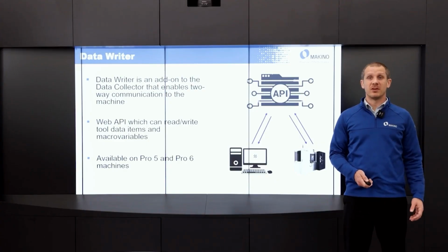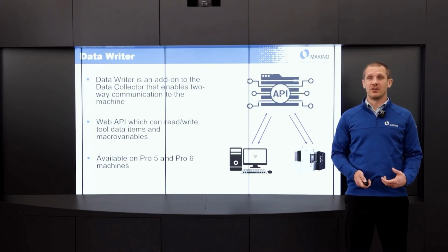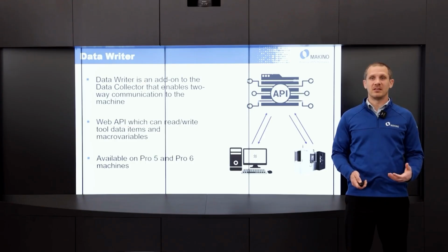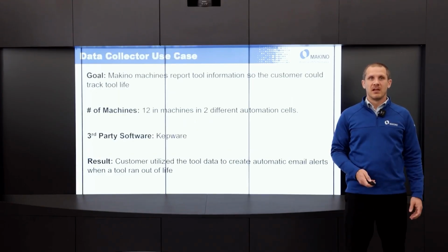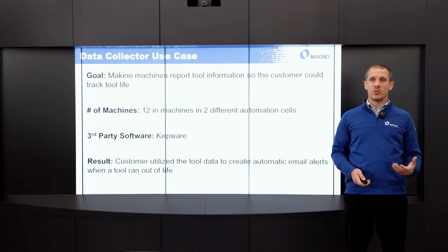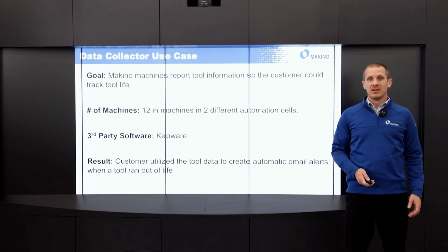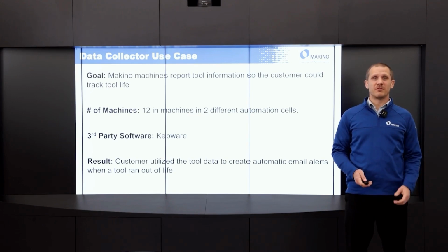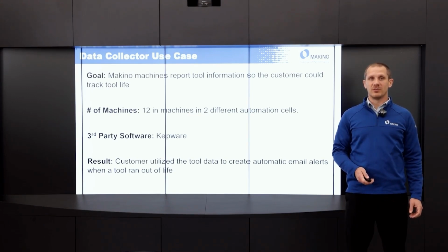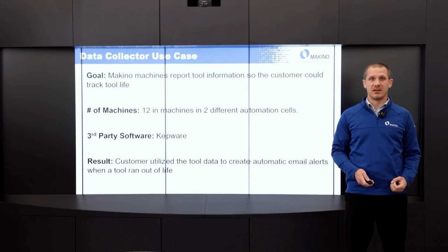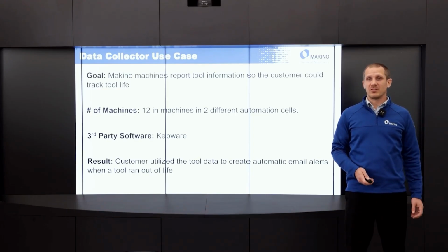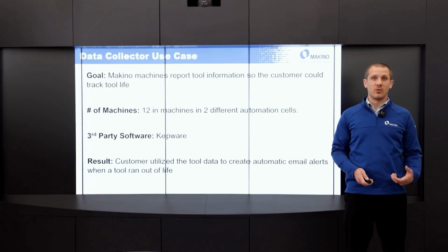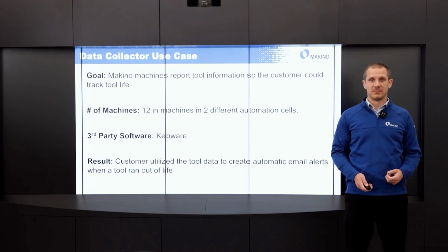Now that we've learned a little bit about what the Data Collector and Data Writer can do, let's talk about some specific use cases where our customers are utilizing these tools in their shop. In use case number 1, the customer wanted Data Collector so that they could track the tool life in their machines. This customer had 12 machines in 2 different automation cells and was utilizing Kepware to aggregate the data. The end result was the customer was able to utilize this data in order to create automatic email alerts when a tool was about to run out of life.